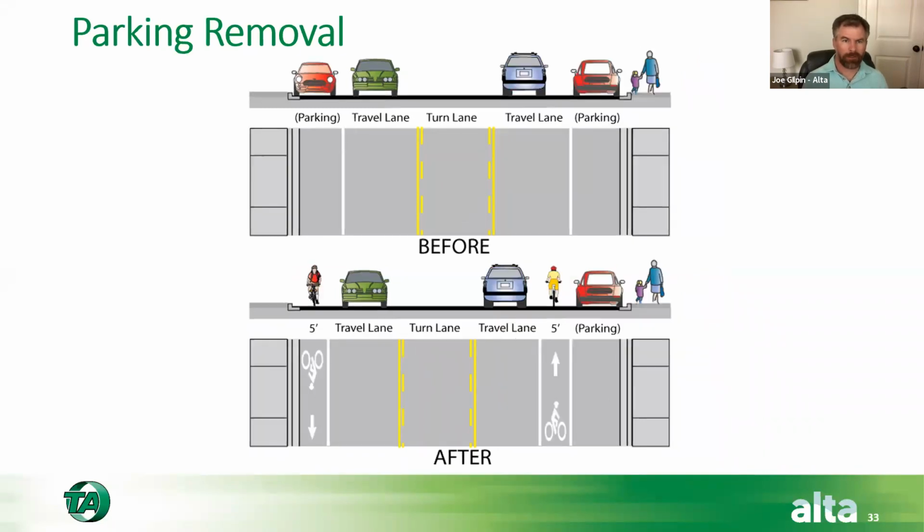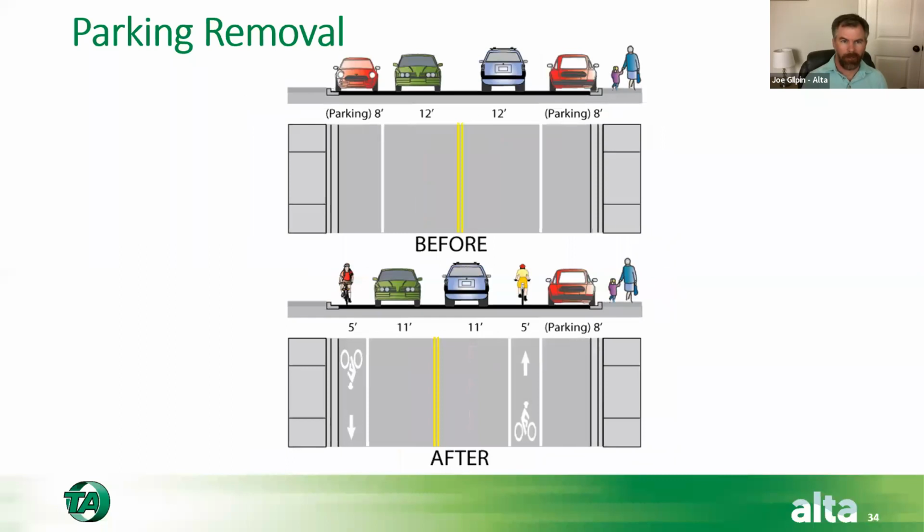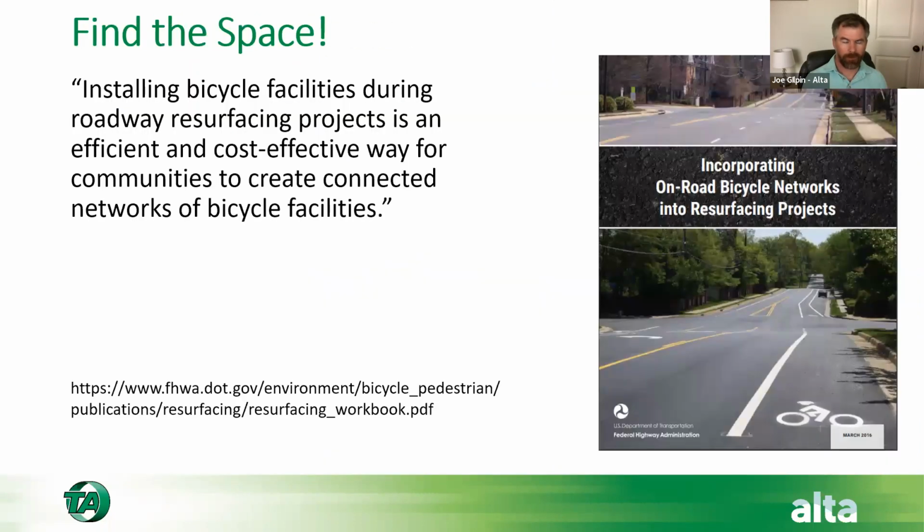Also, we could think about parking utilization, and I see this a lot of times on narrow streets, and people don't want to park on the street because they're worried about that friction of overtaking vehicles. Are their side mirrors going to get taken off? Is there anyone that's going to hit their car? And so we can look at the parking utilization and sometimes figure out where extra parking capacity might exist, do a parking study, figure out, hey, we can take off maybe 1 lane. And I've seen projects where after this goes in, more people park on the street than before because we now have this nice buffer. And as long as that's residential parking for the most part, longer turnover, works very well with bike lanes.